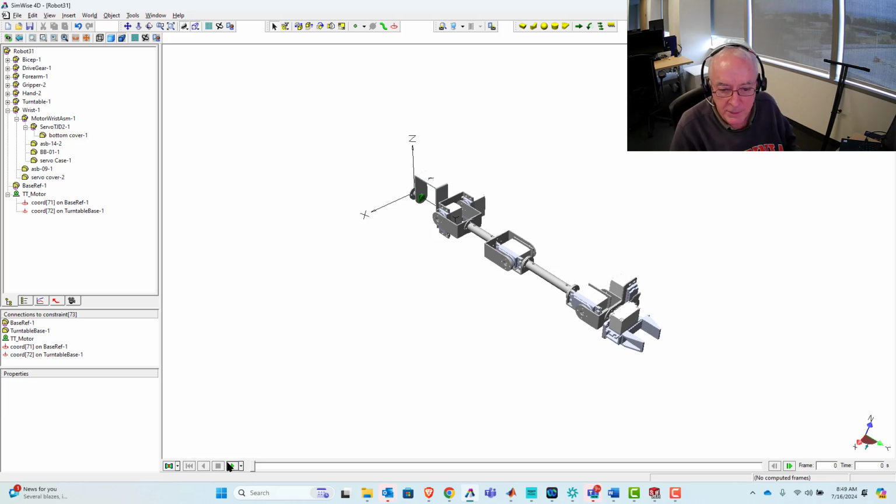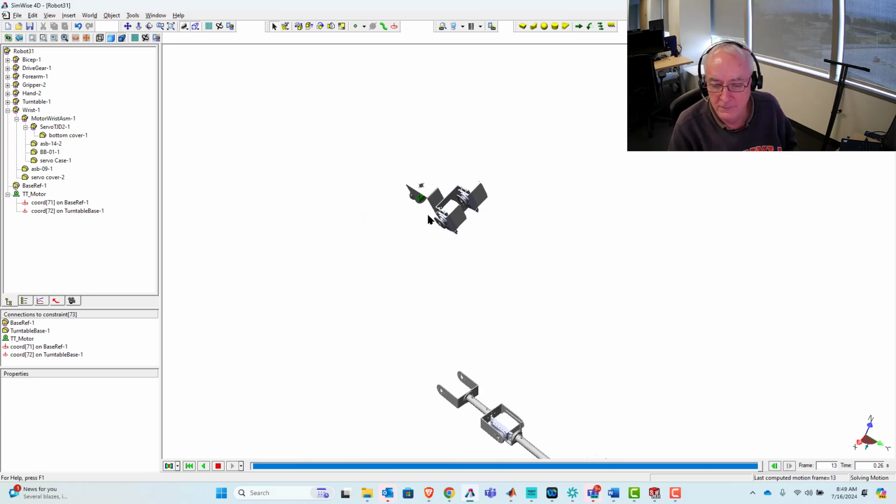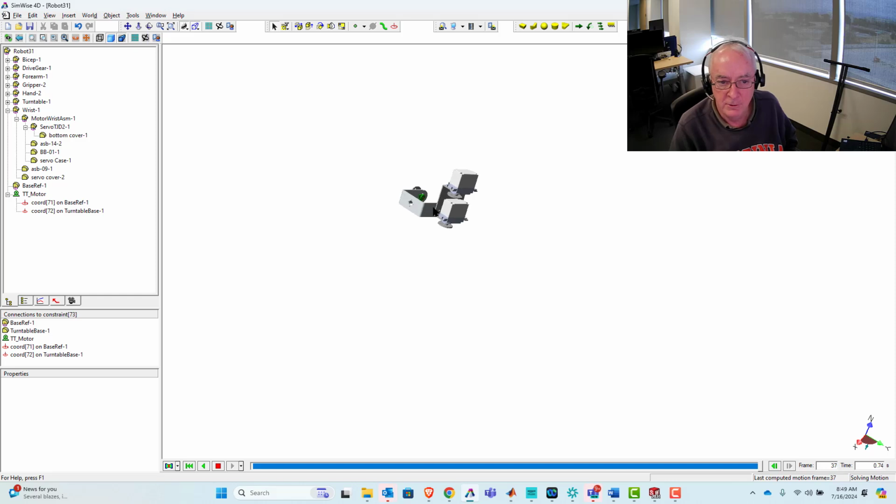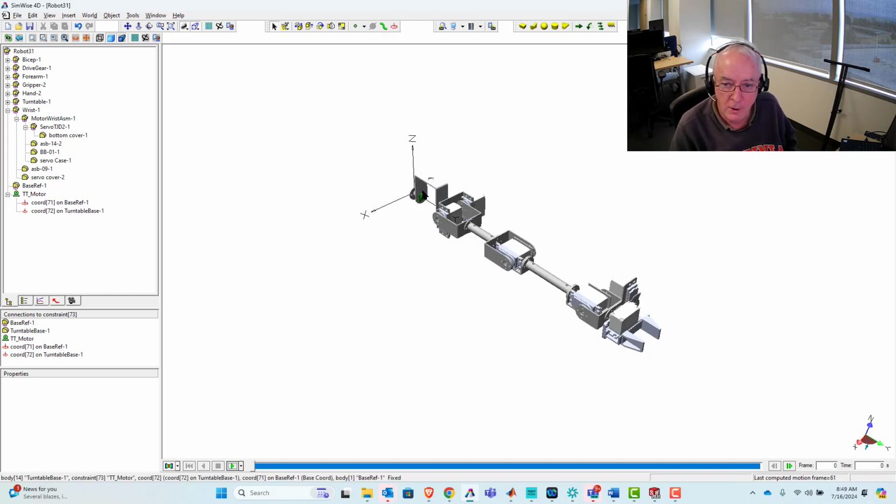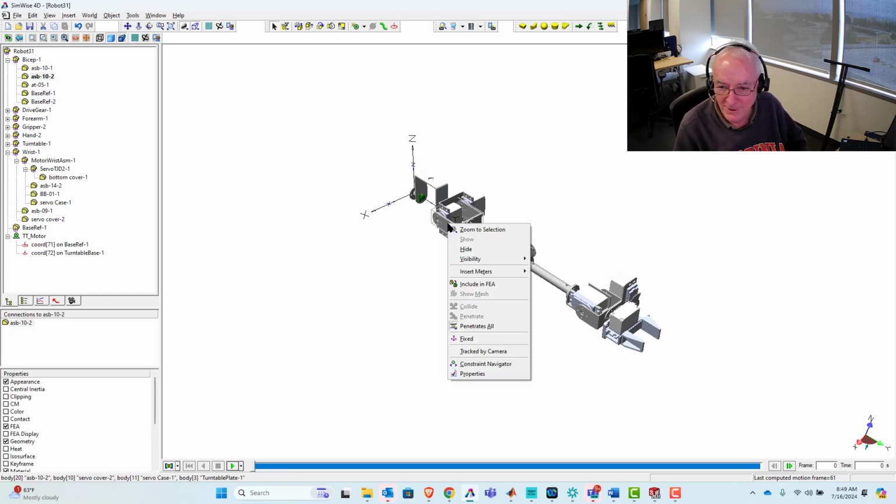Okay, and with that, I think the default on this is set up at rotating at 90 degrees per second. The key for us is that it's almost like we created a tag and said, treat this thing special, because when we bring it into Simulink, it will be a motor. We will control torque and even hook up electric motors and control voltage to make these things move. So, anyways, we're moving pretty well. So let's go do the next one.